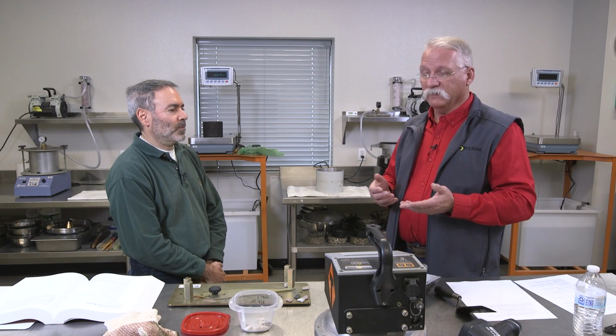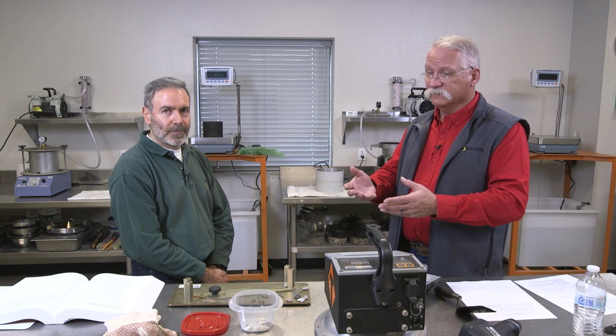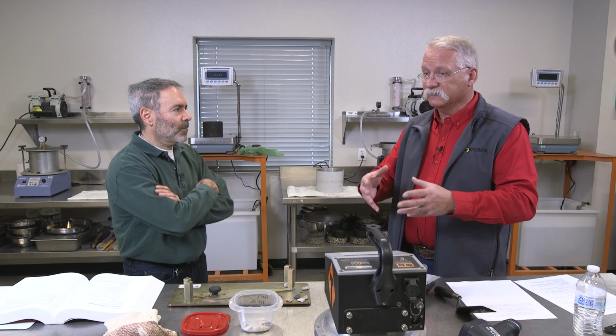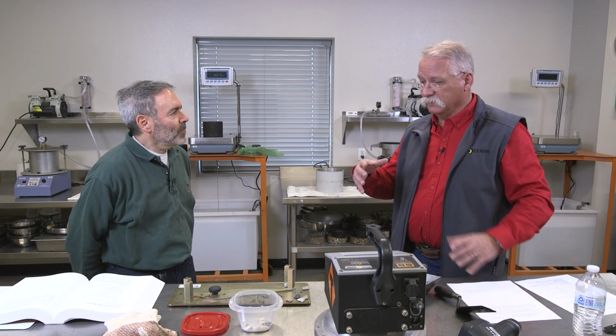Chain of custody is a real important thing for any sample, whether it's a liquid sample or cationic emulsion sample that's being sampled and shipped back, or a binder sample, or a hot mix sample, or an aggregate sample. If that sample is to be used for acceptance, there needs to be a chain of custody associated with that to make sure that it's that sample that gets back and that's the sample that gets tested, and it doesn't get damaged or destroyed or swapped in the process. So real key component. And we typically use the sealed bags in the field and all that kind of stuff, which is a great way of doing that as well.